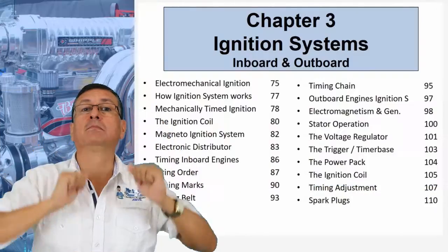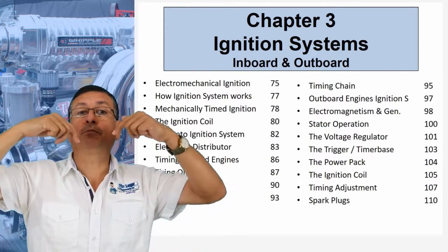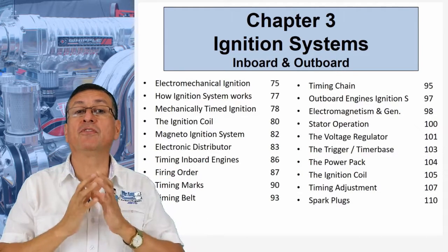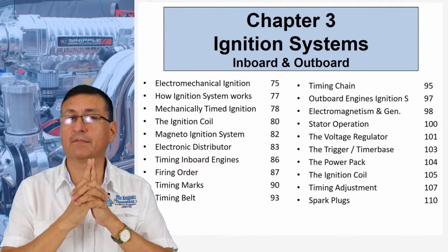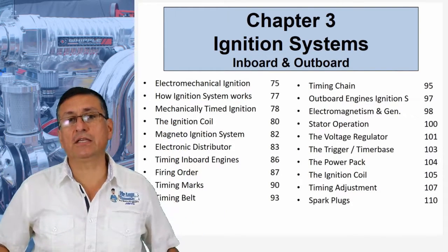Oh, incredible. In some engines like the E-Tech, you remember that video, the spark plug should be in front of the injector in order to improve the performance of the engine. That's very, very important. Yes, my friend, this is in two-stroke engines.